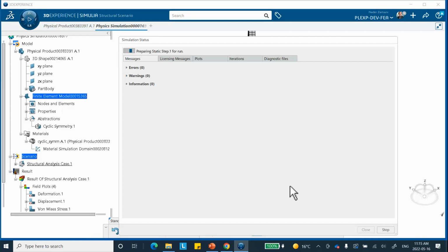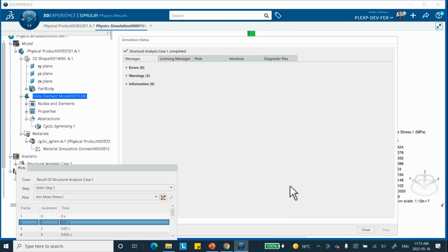By the way, those 2 points and the line that I created in order to define the axis of symmetry and axis of rotation: in all likelihood, I could have used an axis system, created the XYZ coordinate system at the origin, and used the vertical, presumably Z, as the axis of rotation and axis of symmetry. In other words, I didn't have to create 2 points and a line. Just the coordinate system would have been sufficient. I could have chosen the axis for that.